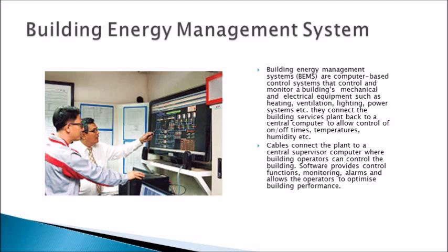Let's focus on the building energy management system. Building energy management systems are computer-based control systems that control and monitor a building's mechanical and electrical equipment such as heating, ventilation, lighting, power systems, etc. They connect the building services plant back to a central computer to allow control of on and off times, temperatures, humidity, etc. In the past, they used cables to connect the plant to a central supervisory computer where building operators can control the building.